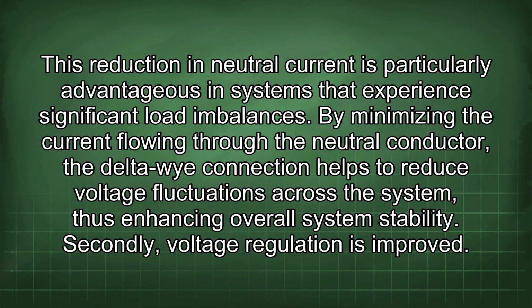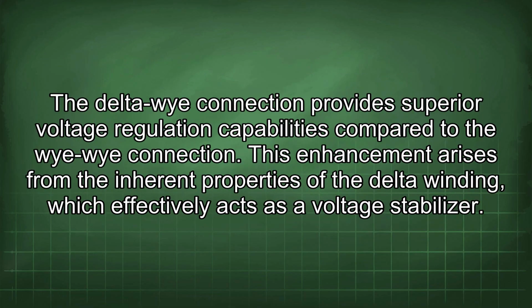By minimizing the current flowing through the neutral conductor, the Delta-Wye connection helps to reduce voltage fluctuations across the system, thus enhancing overall system stability. Secondly, voltage regulation is improved. The Delta-Wye connection provides superior voltage regulation capabilities compared to the Wye-Wye connection.